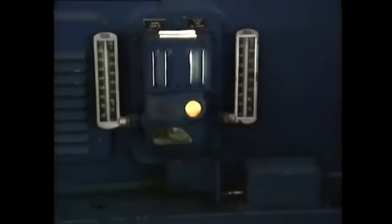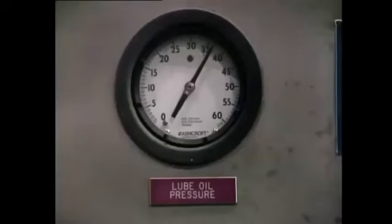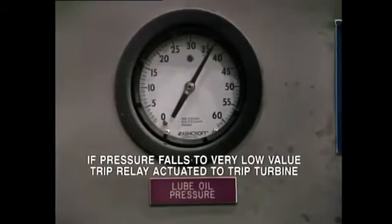Another condition which will cause the turbine stop valve to trip is loss of lube oil pressure. If lube oil is not available to provide lubrication to an operating machine, the bearings will rapidly overheat and fail, with possible disastrous consequences for other components of the turbine and generator. Lube oil is monitored continuously, and if pressure falls to 0 or a very low value, a trip relay will be actuated to trip the turbine. Note that this relay will also prevent the opening of the turbine stop valve if lube oil circulation has not already been established during startup.